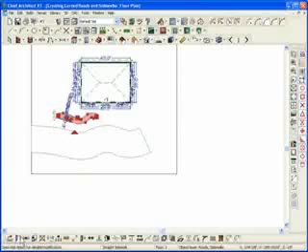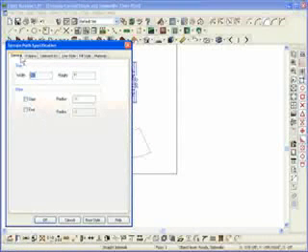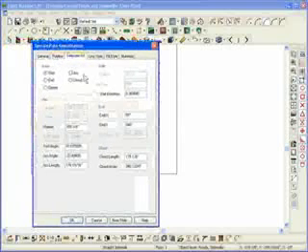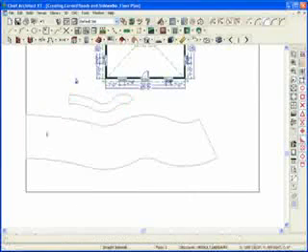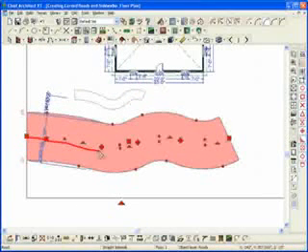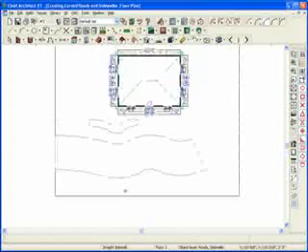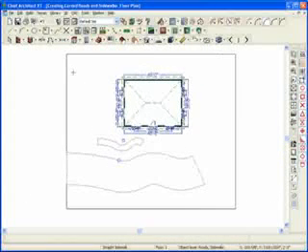And if you open up the dialog for any of those items that you've created, you can then start adjusting the width and things like that. You can also adjust that arc, that white line that you see down the middle of your road, right here. So that's what you're adjusting. You're adjusting that line that's running down the center of the road and the sidewalk. That's the arc that you're creating by bending them. So there's a little tip